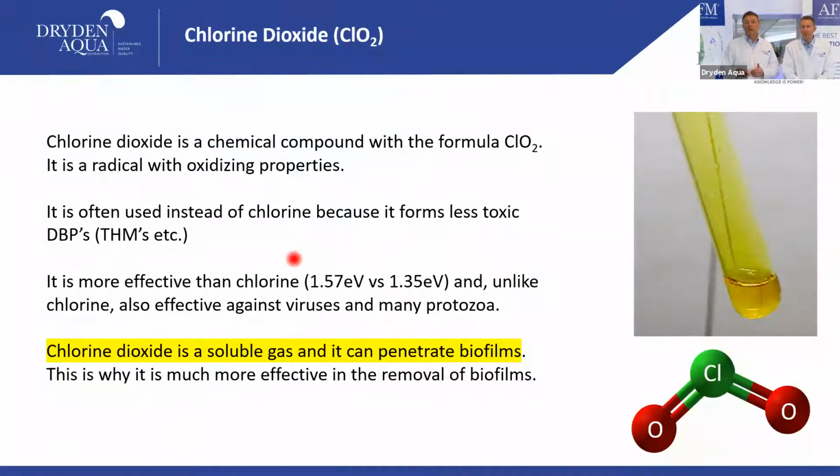Here you see chlorine dioxide, here you see chlorine gas. It has a slightly higher electrovolt potential. It makes complete oxidation. So you can also decrease combined chlorine by adding chlorine dioxide. It's not a long-term solution, of course, but if you shortly have to decrease it, that will work. It will not form disinfection byproducts such as THMs. This is what you see here. So that's a good one. It can build up chlorates, which is why you don't use it continuously, but it's a soluble gas.